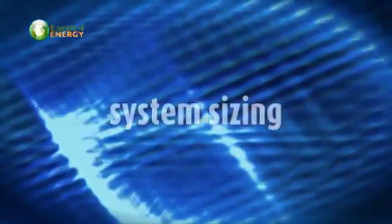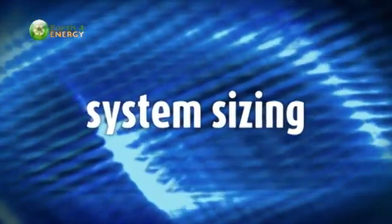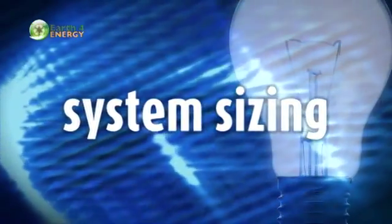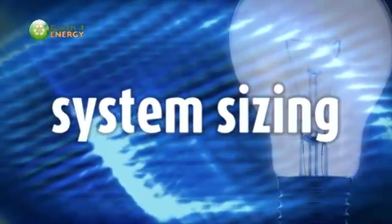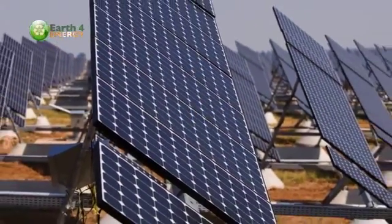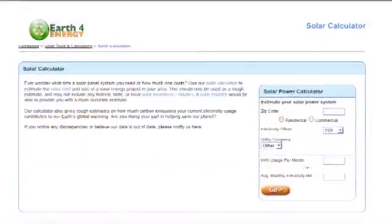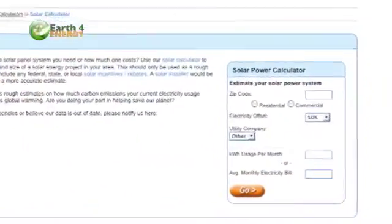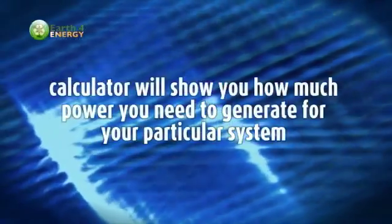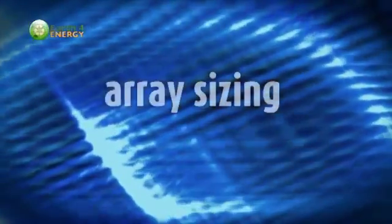Next, we'll go through system sizing, because the first thing you need to do is decide what it is you want to provide power for. You can choose to provide power for just a few lights or to provide for 100% of your power usage. Obviously, the more power you wish to generate, the more panels you'll need in your array. We've included a solar calculator in the members area too, so make sure you check that out when sizing your system. This calculator will show you how much power you need to generate for your particular system. Then we'll go into array sizing.